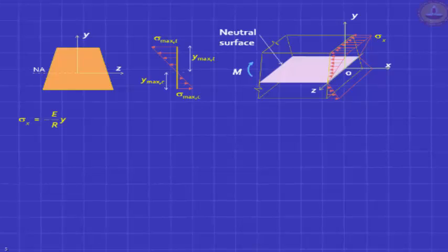And actually, we said it's a function of y, which means in the z direction, in the breadth direction, all layers, all points will have the same strain and same stress. That's a fundamental assumption we are making. So it's actually an entire surface which is getting affected, and so it's a neutral surface. That's the correct word to use.